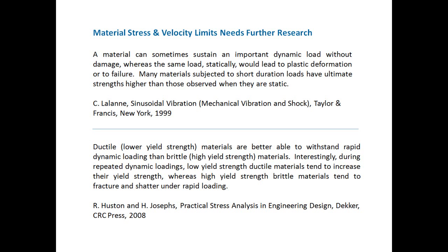Here's another quote. Ductile, lower yield strength materials are better able to withstand rapid dynamic loading than brittle, high strength materials. Interestingly, during repeated dynamic loadings, low yield strength ductile materials tend to increase their yield strength, whereas high yield strength brittle materials tend to fracture and shatter under rapid loading.